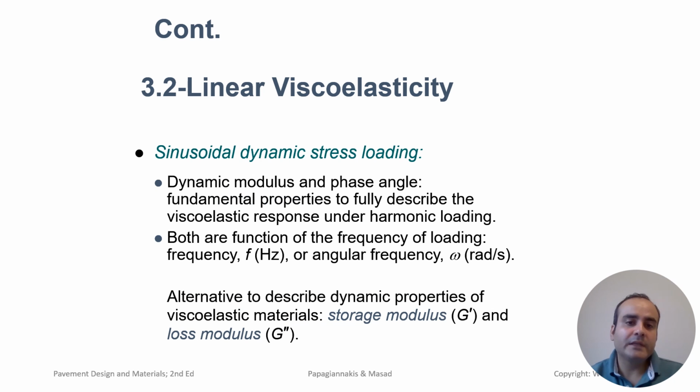So we already know that dynamic modulus and phase angle are both important fundamental properties to fully describe the viscoelastic response under dynamic loading. Both are functions of the frequency of loading, which can be frequency or angular frequency. An alternative way to describe dynamic properties of viscoelastic materials is storage modulus and loss modulus.